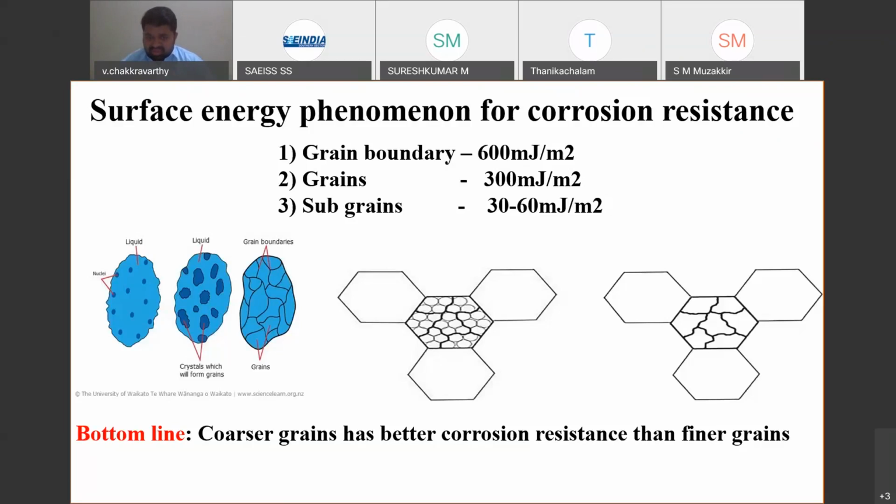For mechanical applications. If your material is cooled in an open environment, for example, if it is in red hot condition and you just leave it as it is in the open, the material will cool down very slowly. Automatically that will result in coarser grain formation. Coarser grains don't have enough mechanical properties, because they can easily undergo fracture, but fine grains will never undergo fracture easily.